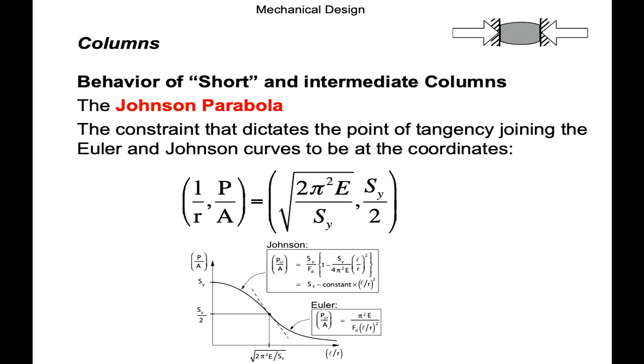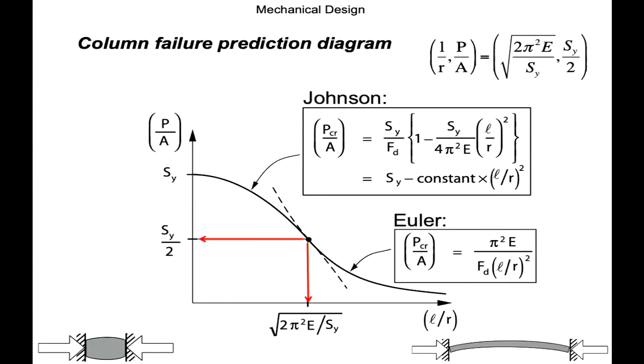And in very small text is the overall equation. I'll move ahead one, you can see it a bit better. So the critical strength, the critical load associated with a particular column with a section area A, can correspond to this equation as far as the Johnson formulation is concerned, with yield strength corresponding to the upper limit, when we have a very, very, dare I say, infinitely thick, infinitely stumpy column.